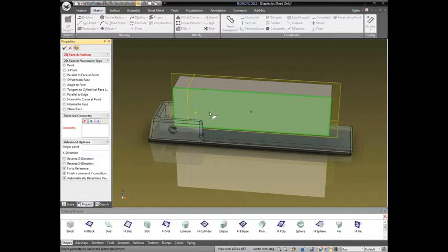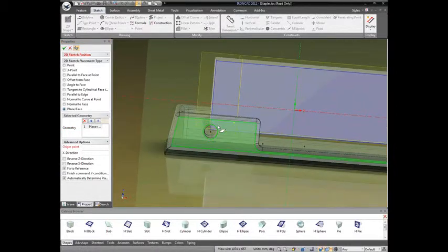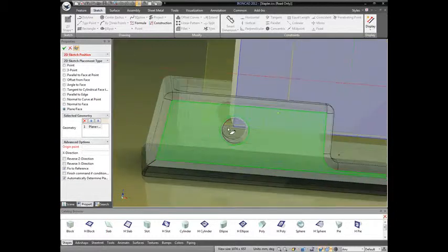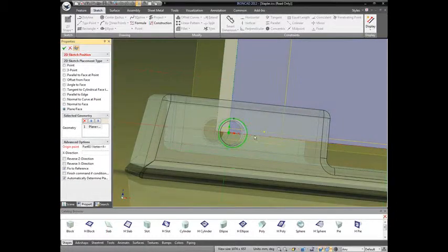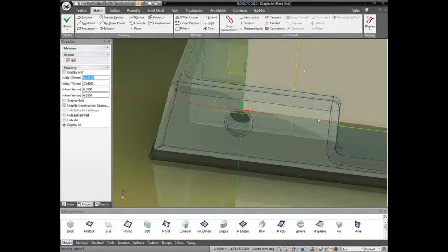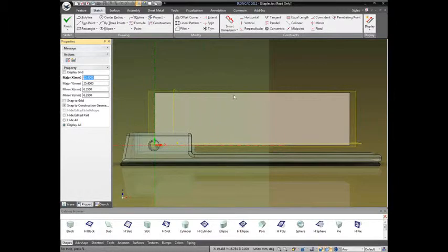Okay, so I'm going to put in a sketch here and go by a plane and a face, and then I'll set the origin down here on the corner. I'm just going to set up basically, if I get that corner, hello, a lot of geometry converging here. Okay, going to set up a sketch for a surface here and show you how the surface will even be part of the solid, or a feature of the solid.